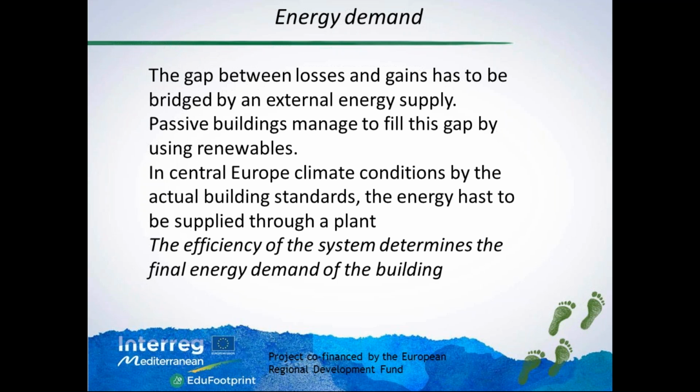And this energy demand is not only determined by the energy needs, so by the characteristics of the envelope, but also by the efficiency of the heating plant. At the first stage, it's very important to reduce the energy needs of the building, and afterwards it's important to increase the efficiency of the plant.